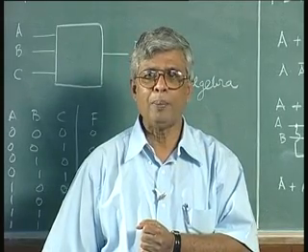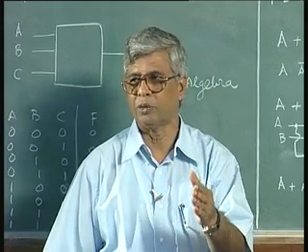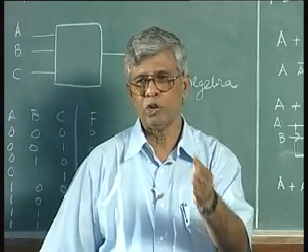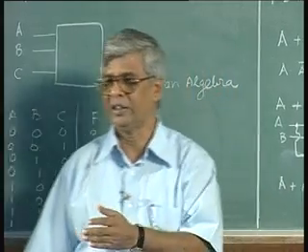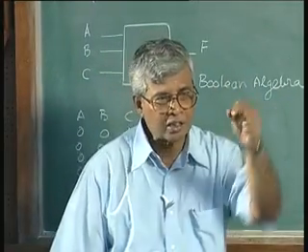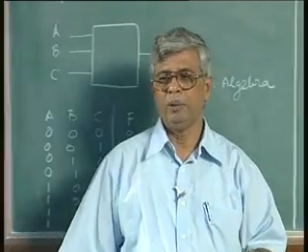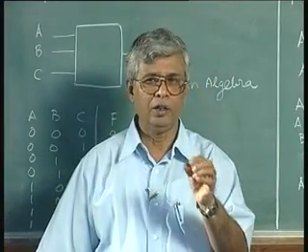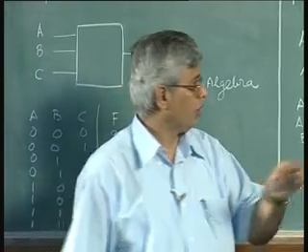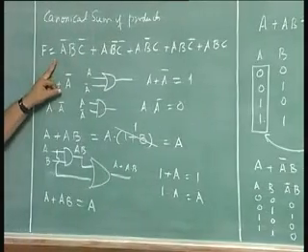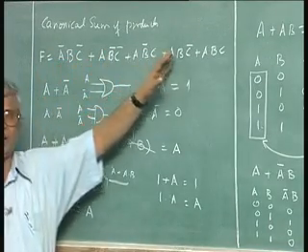So, how do you reduce the complexity of an OR gate, the number of inputs to the OR gate? By reducing the number of product terms, so that the total number of terms for which you need to get an OR function is reduced. And each of these terms, which are AND gate outputs, can be simplified by reducing the number of variables in that AND gate. So, for example, if you take this logic function, I can reduce this in 2 ways. There are a total of 1, 2, 3, 4, 5 terms.